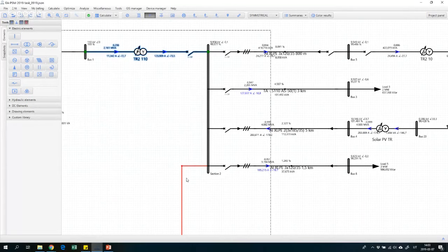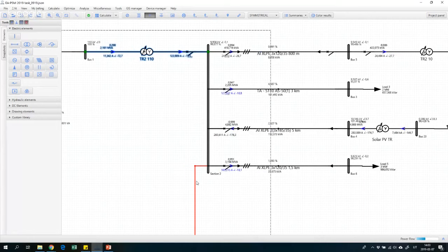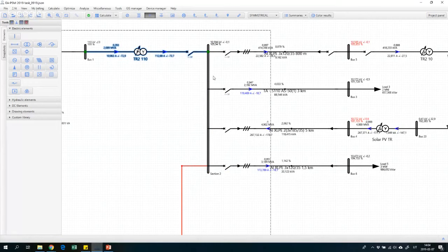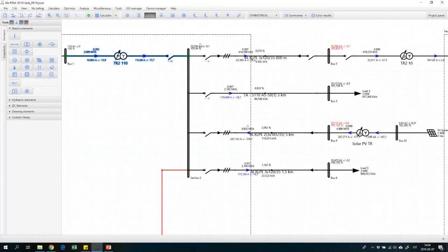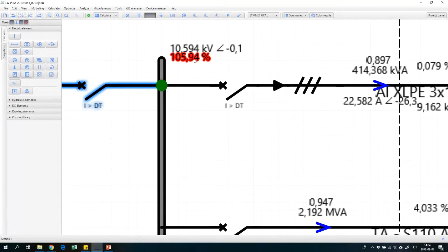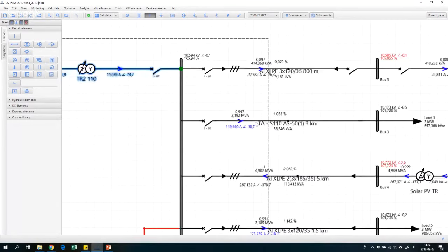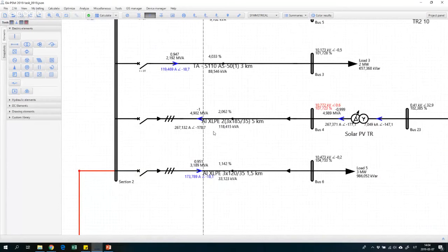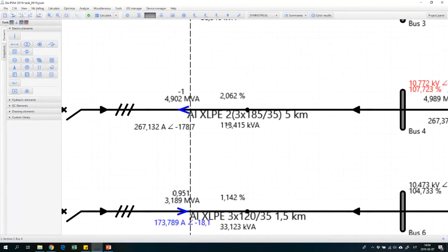Of course, all the loads like the solar power plant will also affect the voltage, so it will be a little bit higher than nominal. Okay, so in this case, I see that my voltage is now almost 6% higher than nominal. So this, of course, as I have mentioned, will affect currents and voltage losses. So power losses now are only 84 kilowatts. So again, as you remember, in the beginning it was 160 kilowatts. Now we only have 84 kilowatts.